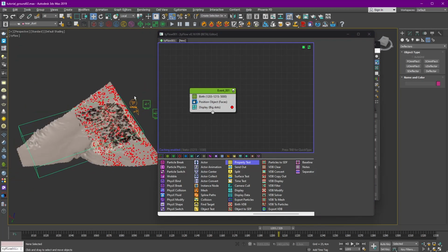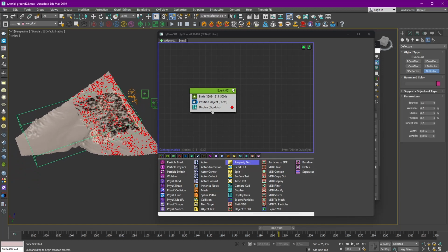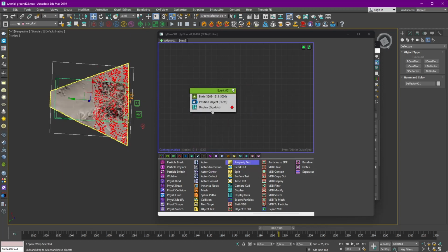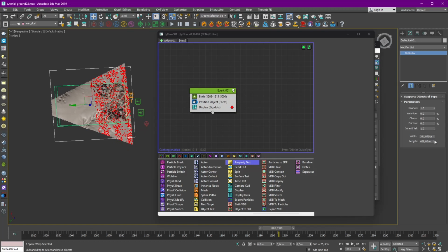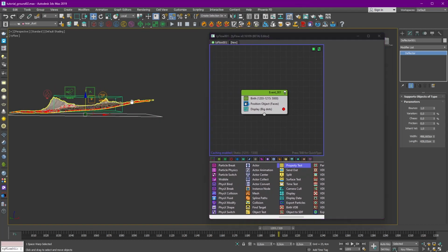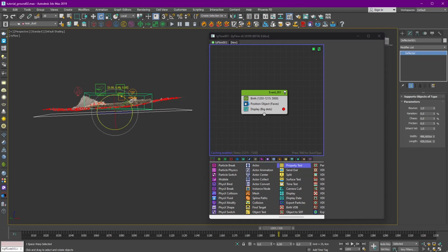So next step, we need to create deflectors which will kill the unnecessary particles, so our system will stay clean and efficient. So the system doesn't have to keep calculating all particles, even those which are under the ground somehow or behind the camera. So we need to create several deflectors and place them like this, one below the ground with some gap. Yeah, like this.